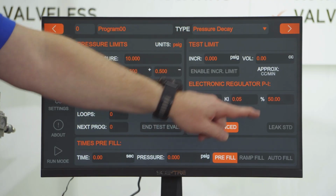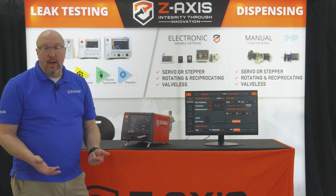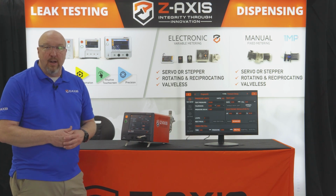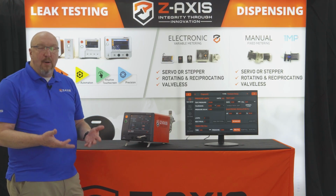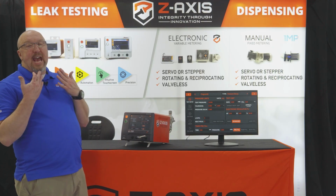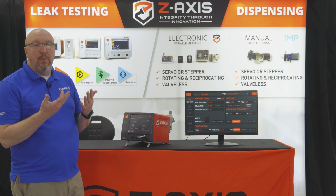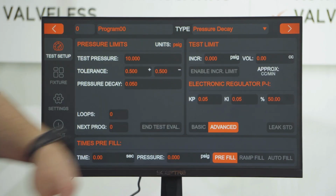KP, KI, and a percentage of feedback. Think of it like the KP is the throttle on a car, and the KI is your reaction to that throttle. So as you get up to speed, how much do you feather off the pedal to stay at speed? Do you let off the gas? Do you make quick reactions, or do you slow your reactions so that you get up to speed and stay nicely at speed? That's how you can think of these two values.